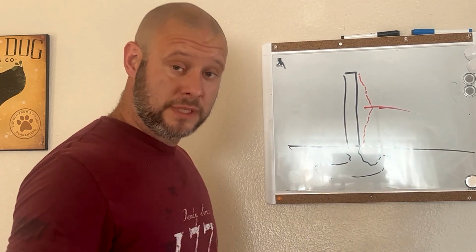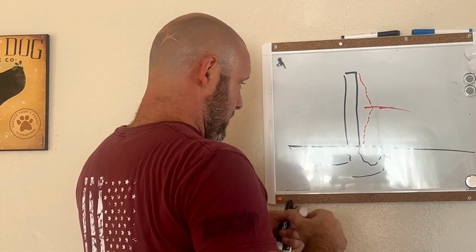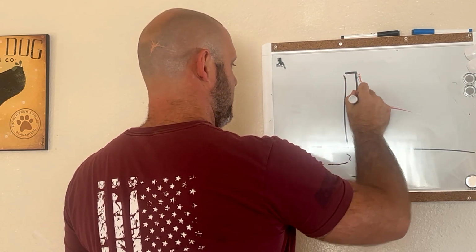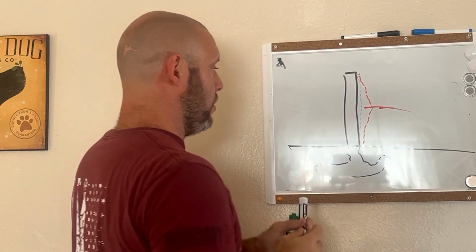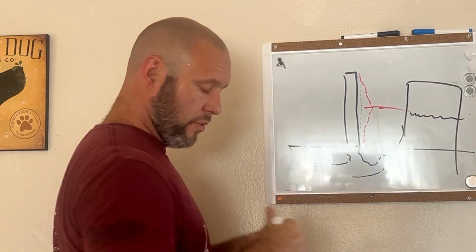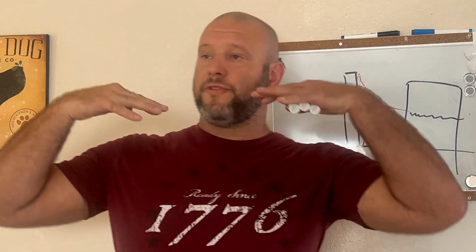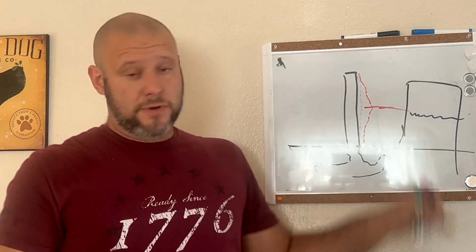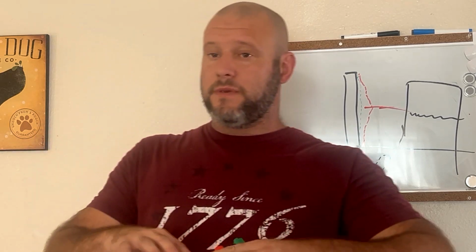But you know what else helps straighten it up? If you're just starting to notice it, if it's not this exaggerated, right? Let's just say somewhat like that. And I'm looking at a retaining wall, and by looking at the CMU blocks, I can see a crack running through it, but it's not quite pushing out. Carbon fiber reinforcement is a phenomenal repair for something like that. They pop those carbon fiber strips on, and it increases the lateral resistance and the strength of CMU or block walls.